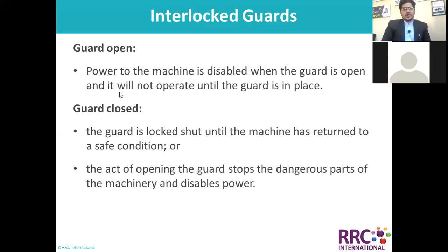Another type we have is interlocked guards. And I always encourage companies that this guarding must be done by the manufacturer, instead of locally fabricated guards that are poorly designed and sometimes don't even suit the machine, even if you paint them and try hard. They are not the way they should be. Sometimes the material quality is not as per the design features, because the manufacturer is responsible to make sure whatever material is used complies with all international standards.